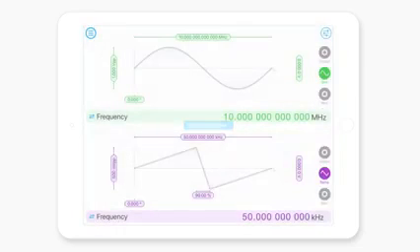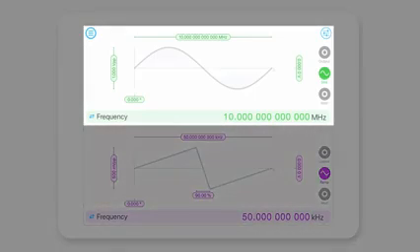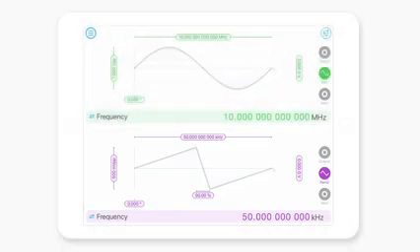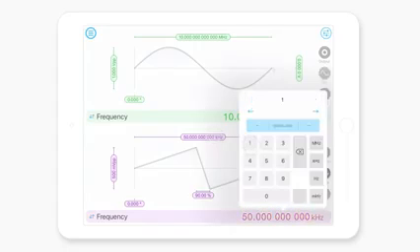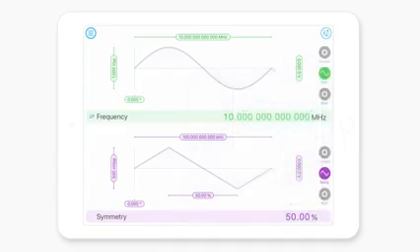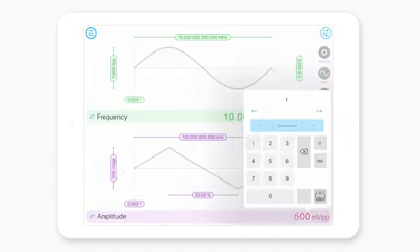So when you first launch the instrument, you'll see that it is divided up into two sections. Up the top, we have the settings for output channel 1, and down the bottom, we have the settings for output channel 2. From here, you can configure pretty much every parameter that you need, depending on the waveform. So for the sawtooth wave down the bottom, we can tune its frequency, its symmetry, its amplitude, and things like phase.